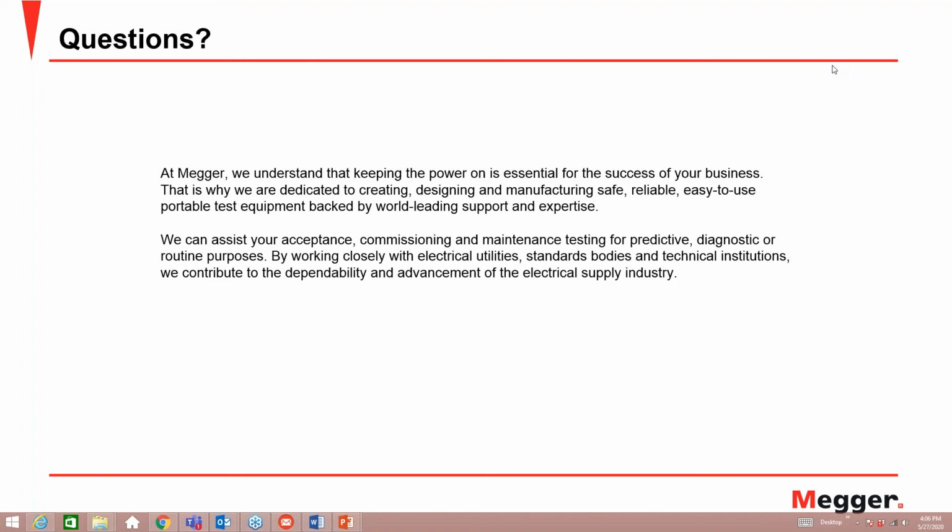Now, however, one thing to keep in mind is that if you are using these batteries in substations where NERC rules apply, you must be able to get to the post based on your NERC requirements. So if these types of setups don't allow you to get to the post, you cannot use these batteries in substations where NERC applies, and that will be any substation that has protection equipment that connects to the bulk system.